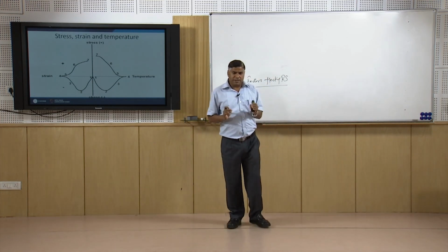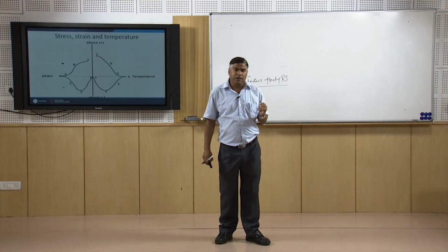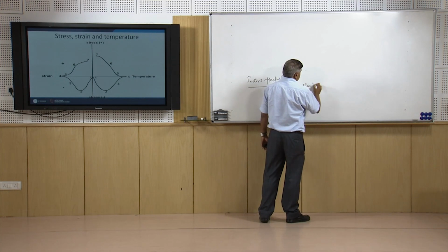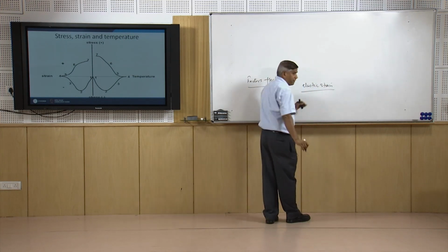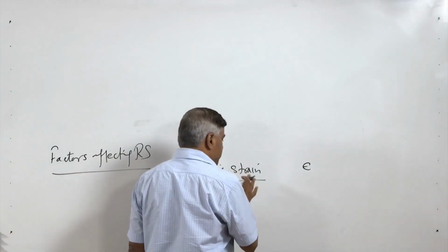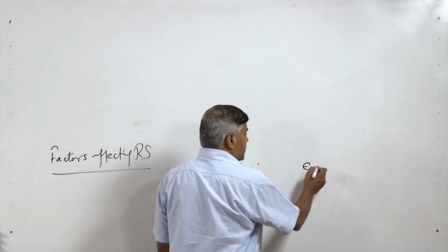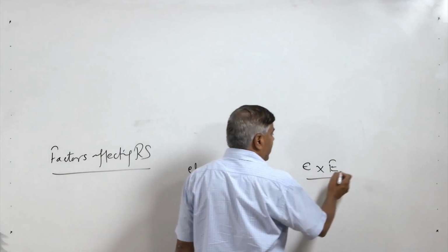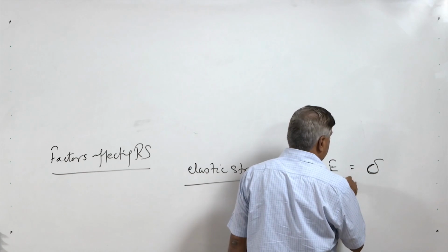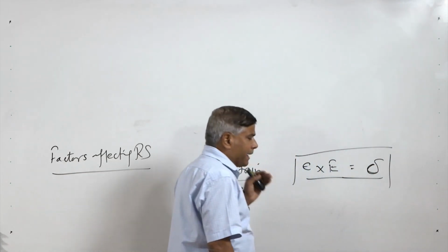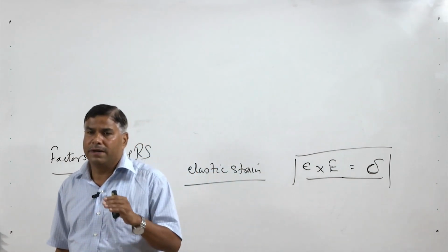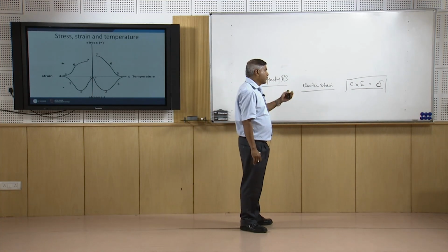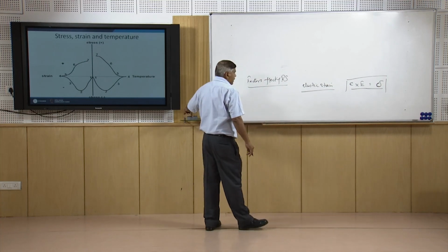One thing is important: residual stresses happen due to the locked in strain, and the locked in strain magnitude can be maximum up to the elastic strain value. So, the maximum strain that can be locked in is up to the elastic limit, and if it is multiplied by the modulus of elasticity, we can find, for the given material of the weld metal or of the base metal, the maximum magnitude of the residual stress. So, the maximum magnitude of the residual stresses is equal to the elastic stress magnitude, and above that, if the stress is more than that, then it will cross the yield stress value and the material will be subjected to plastic deformation.